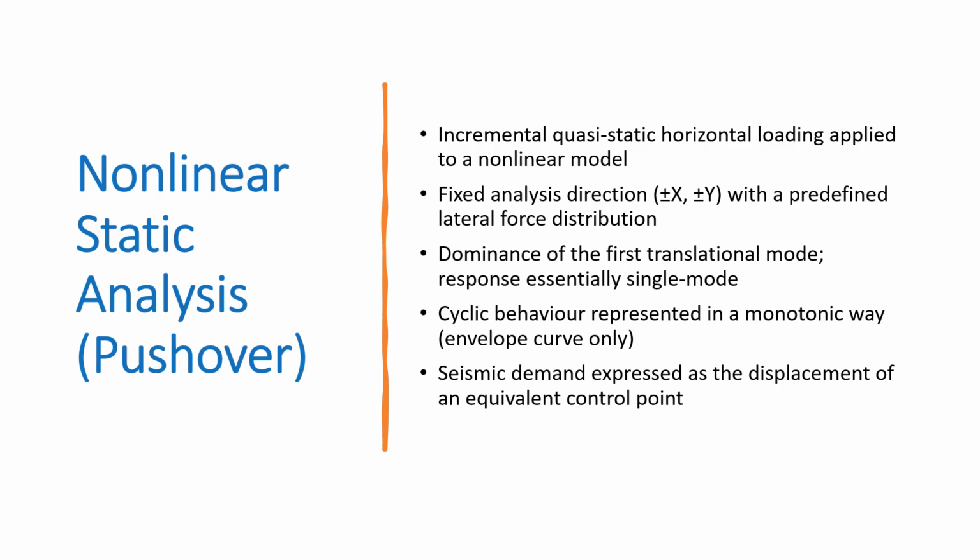Pushover analysis provides the response in terms of a capacity curve obtained by an incremental quasi-static application of horizontal loading to a nonlinear model.